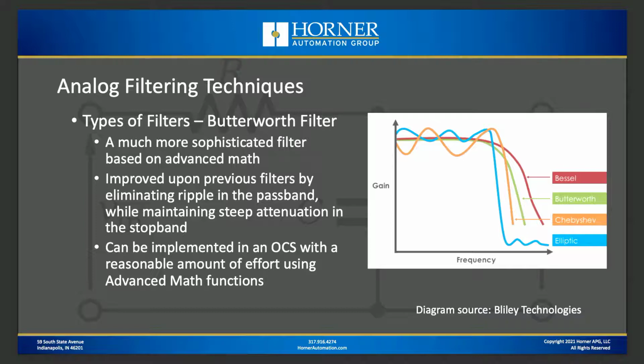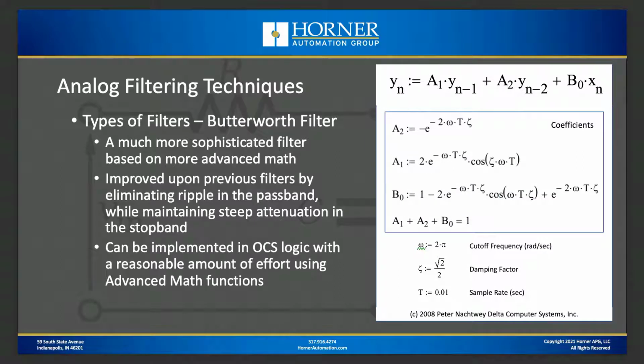Now you say, how am I going to implement something like that in an OCS or a PLC? Well, keep in mind the OCS supports advanced math, so it's perfectly capable of handling the types of calculations that are required for a Butterworth filter. Courtesy of Peter Natchway from Delta Computer Systems, he was kind enough to post his details on implementing a Butterworth filter in a device like a PLC or an OCS.